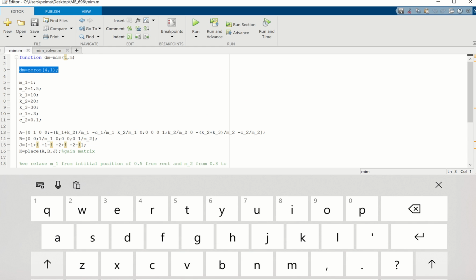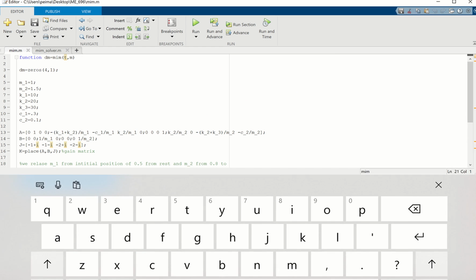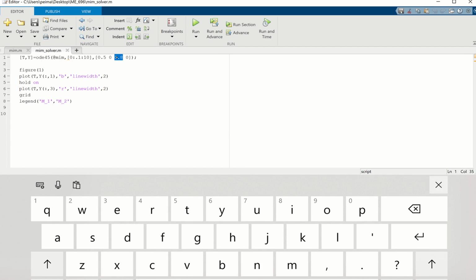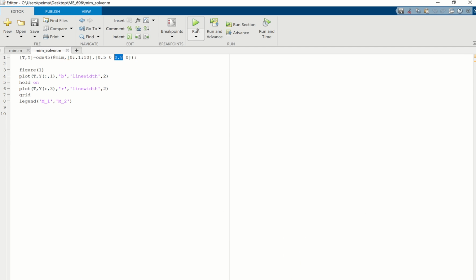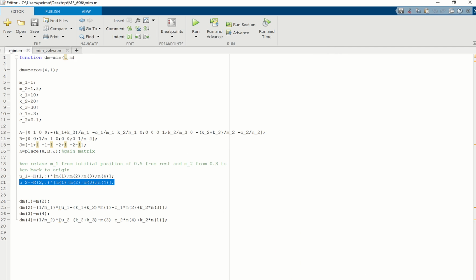Here we go, we generated the code here for you in the previous class. Then we designed the U1 and U2 by a state feedback control law. I released the system from an initial position of 0.5 for X1 and 0.8 for the second one. For refreshing your mind, we wanted underdamped behavior when you release it. Why? Because Ackermann's formula, remember I told you, works for SISO systems.